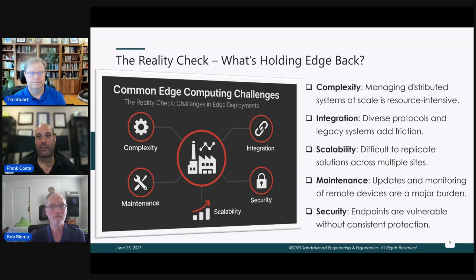The integration. You're talking about pushing it to the edge. These devices have to be able to talk multiple protocols, and especially with legacy systems, that can add issues. You might have what looks like a spider web coming into these edge devices, but once you contextualize it, you go through the exercise of setting up maybe a UNS or a CDM protocol. That transformation happens at the edge, so everything coming off the edge is talking the same language back to the system.